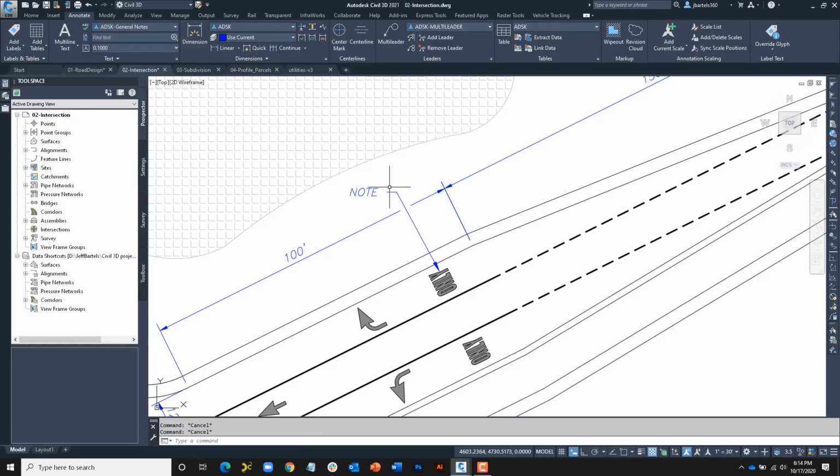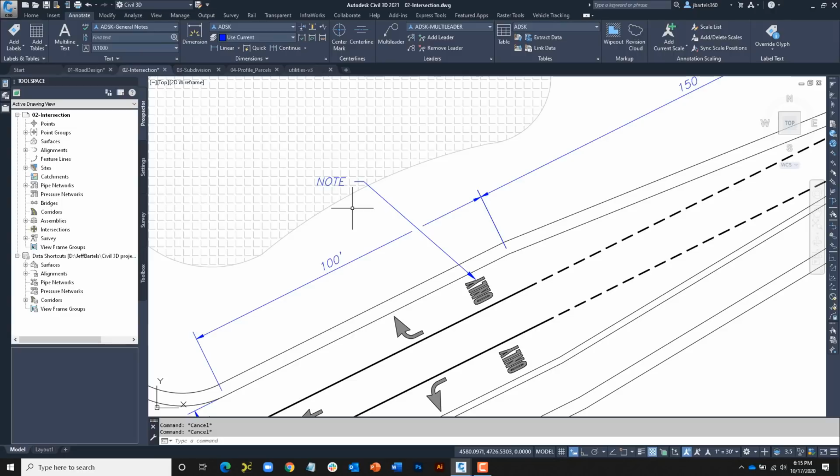Now, you may be wondering, will this work with Civil 3D labels that are in a dragged state? Unfortunately, it will not. So this trick is not going to be suitable for every situation. That said, no trick ever is. I'm going to select this label one more time and we'll drag it out. As our drawings become more busy, we may have no choice but to place labels in an area where we have congested line work. Now, Civil 3D labels have a masking feature to hide the objects behind the text. We can do the same thing with our multi-leaders.